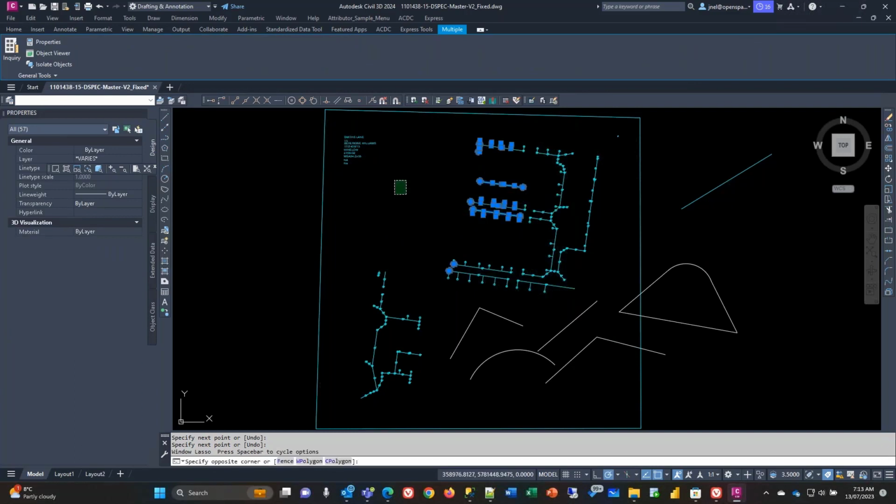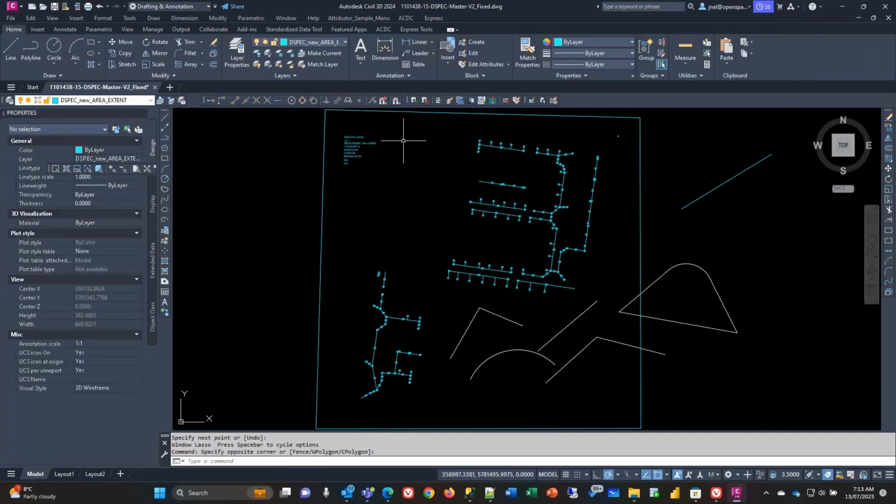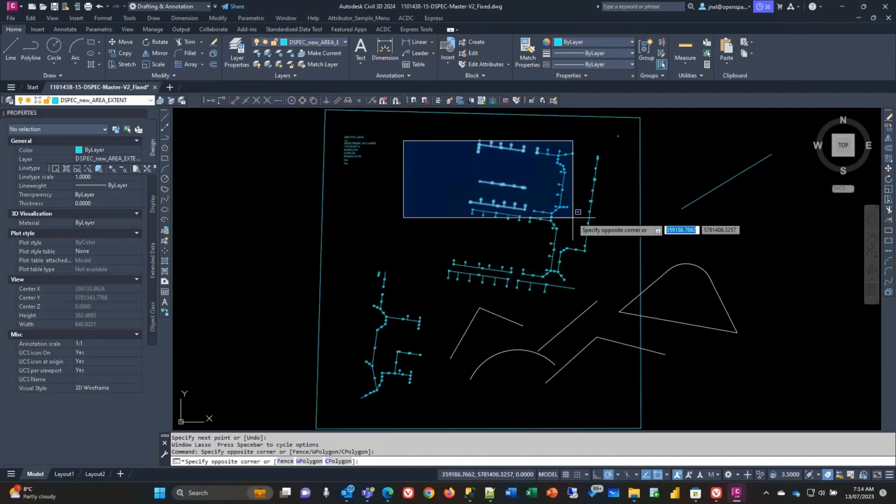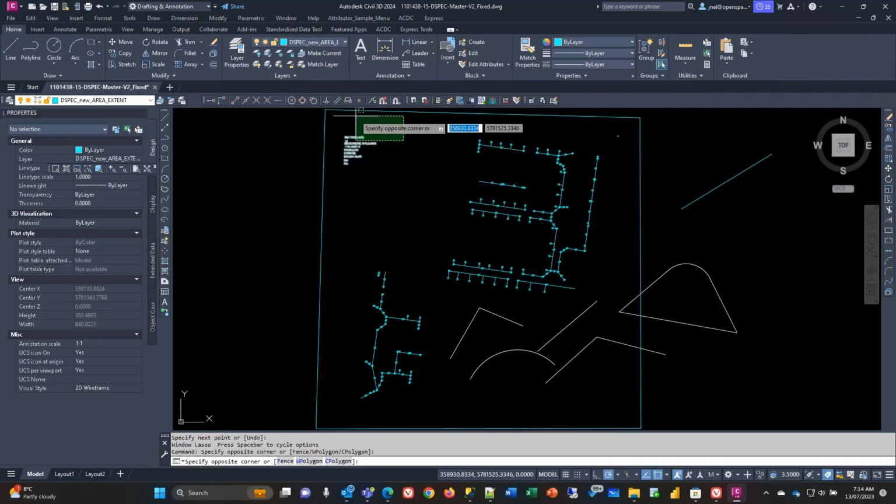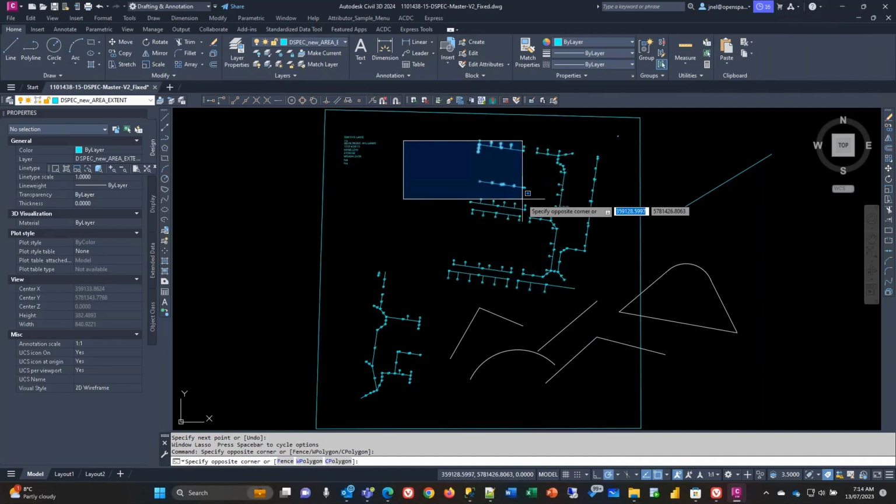Typically how you would work with selection in AutoCAD is you would single click and leave the mouse button. So now you're in a selection mode. Now you'll see the color change there, and I'll talk about that in a moment. But then you can go and select there.